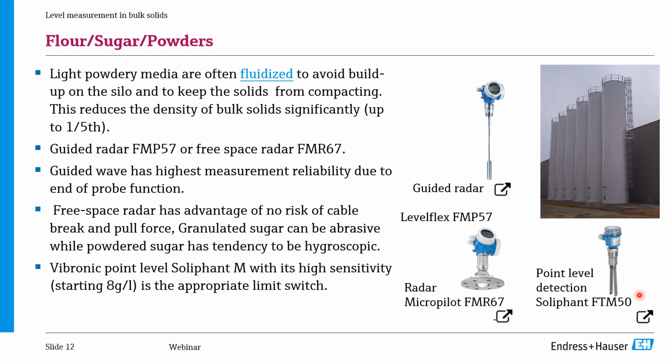And for level detection, pretty straightforward. We always use the vibronic sensors, such as the FTM50, which has a very high sensitivity for very low density. So this is a very interesting product to really increase the safety of your operation.